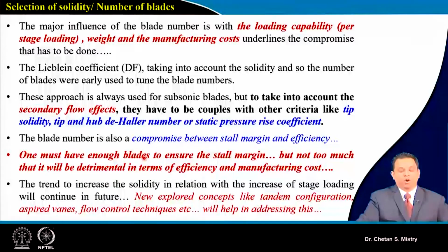Now it says one must have enough number of blades to ensure the stall margin, but not too many blades, as that will have a detrimental effect on efficiency and manufacturing. So there, it says you need to play with these numbers.